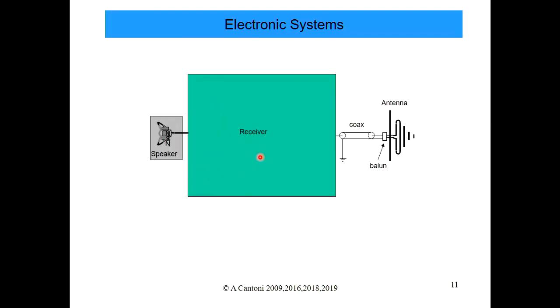Another system here, perhaps on the other side, is the receiver. Again, we have this antenna, which is a large element modelled by a 1-port. We have the coax. We also have the receiver, which could be modelled by a 2-port. And then on the other side, the speaker, to convert the electrical energy into sound energy. Again, this could be modelled by a 1-port. But it's not just a pure electrical system with small elements. Actually, compared to the acoustic frequencies, it is fairly small, but it's also got a lot of mechanical parts and magnets and stuff like that. So we have to develop a model for that which we can use in circuit theory, so that we can predict how things are going to work.